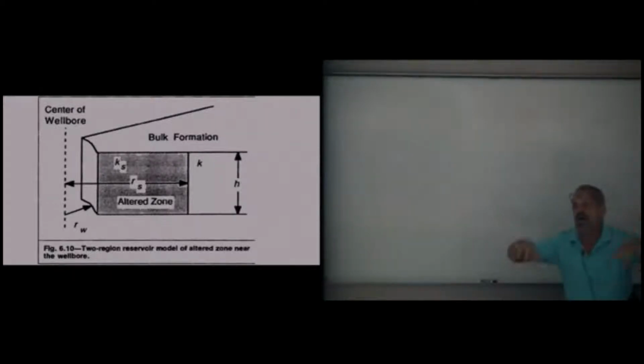So I have two controls on the pressure at the bottom. I can choke back the surface conditions on the outflow on the annulus side. So I have another handle. I don't necessarily have to weight up my mud to control the bottom hole pressure.